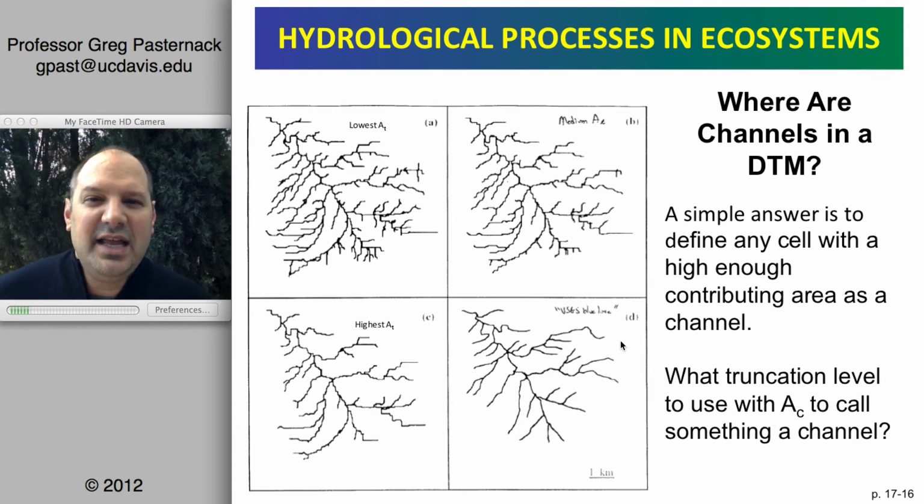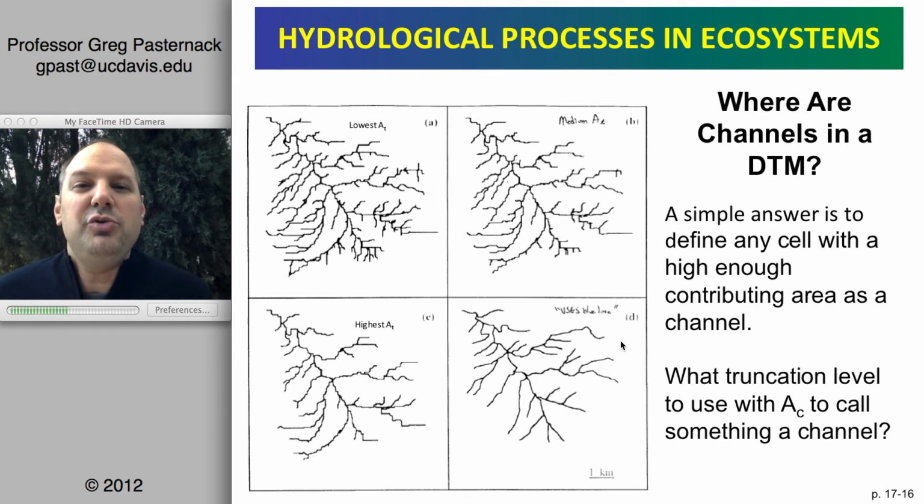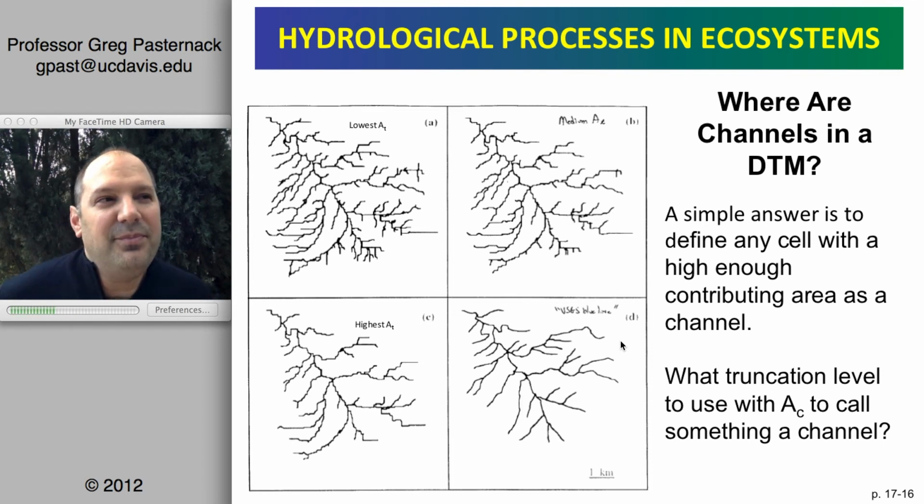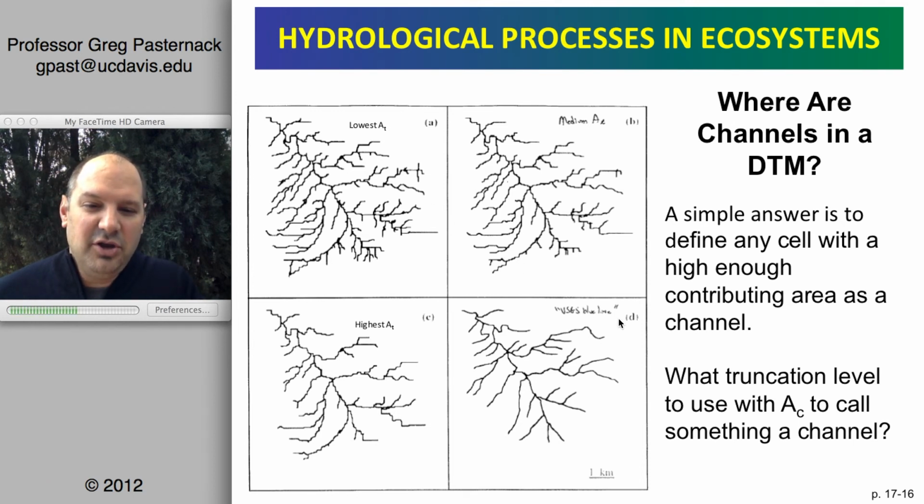So if you look at a United States Geological Survey topographic map, you'll see that the map includes blue lines that represent the presence of, like, perennially wetted channels. Now, usually there are geometric channels that are further than that, and remember from the variable source area concept, the occurrence of overland flow, which may also include channelized overland flow, it varies, so it isn't necessarily just fixed. But you can certainly look at the blue lines and say, well, among that, this highest contributing area approach is the closest. It's not perfect, but it's the closest.